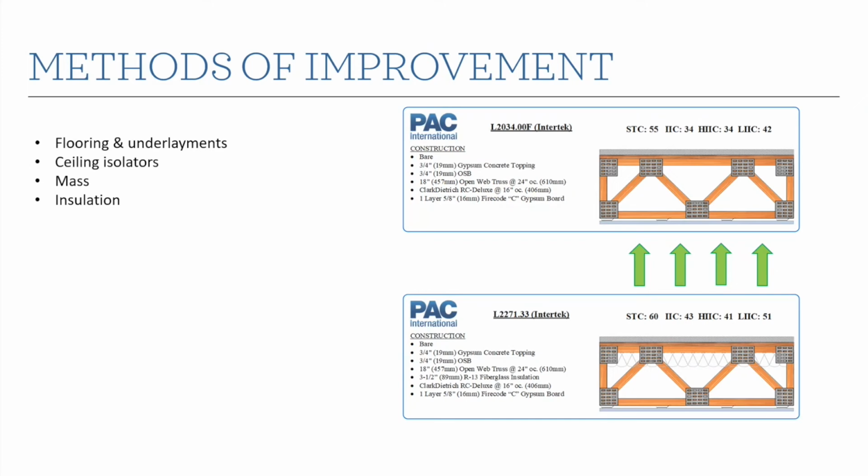The other thing to look out for is if you're dealing with UL fire rated designs like this open web truss, there's often a maximum thickness for your insulation. And if you go beyond that, you have to change things about the assembly. Typically, that's reducing your channel spacing. So by increasing the insulation, you may incur other costs, material and labor costs, because you've got to add more channel to your ceiling or something like that.